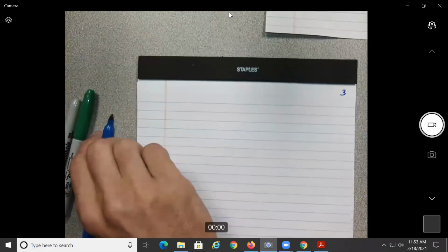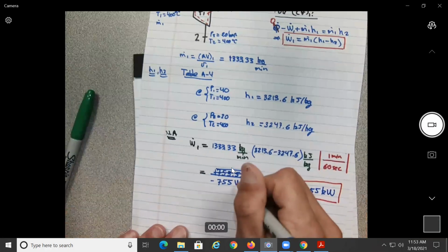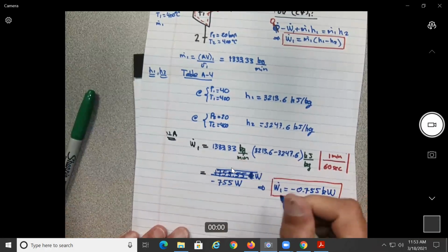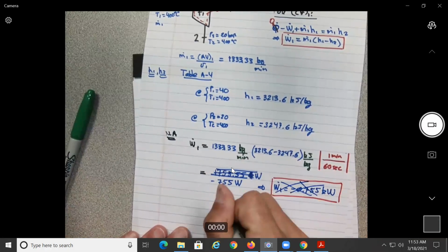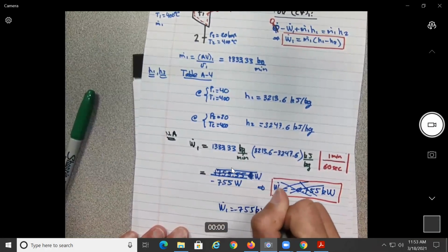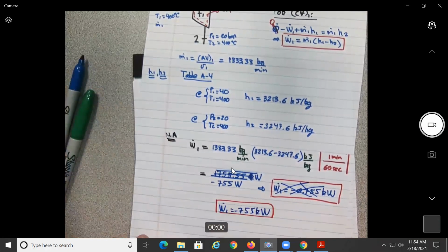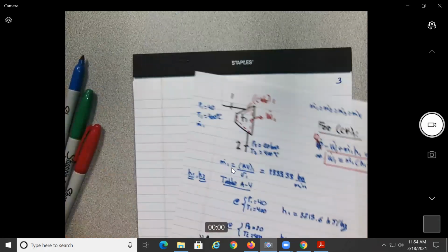Okay, so for turbine 2, okay, guys, one good observation, I didn't pay attention. This is kilojoules, this kilo one cancels, so it's kilojoules per second. So this should be already kilowatts over here. All right, so let's remove this one. This should be here. So let me scratch this one, and just at the end we have 700 minus 155 kilowatts.